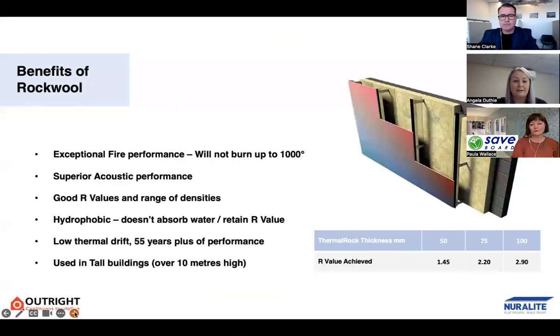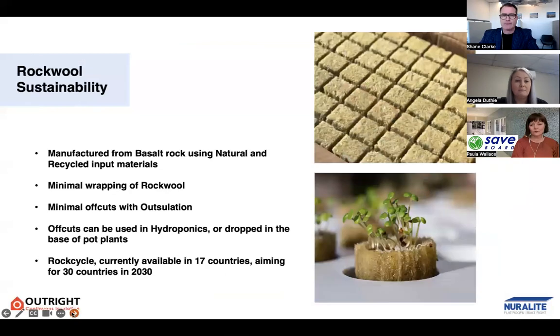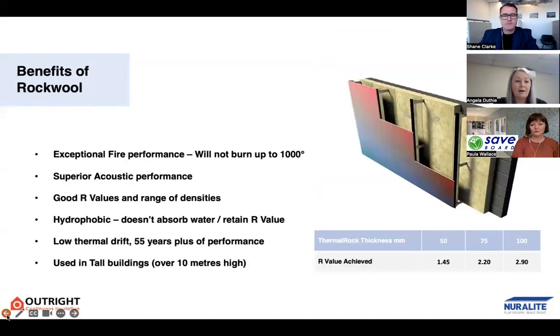Next slide. So the benefits of Rockwool, it's actually a multifaceted product. So it has exceptional fire performance, superior acoustic performance and really good R values. Being hydrophobic, it doesn't absorb water, but if it does get wet, it will retain its R value.